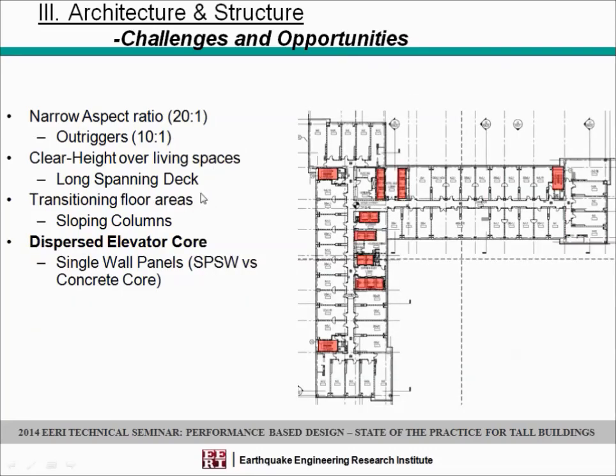The other aspect was, as I think others have hinted, when you have different core configurations. This one by design originally had different cores, which made it challenging for the concrete. Normally in concrete you want to form a spine, and you have the concrete forming, jacking systems that give it the cost benefits. Here was the distribution of cores because of the many programs and the privacy of the programs and the access that's needed in elevators and stairs and multiple height spaces in between and sky lobby.